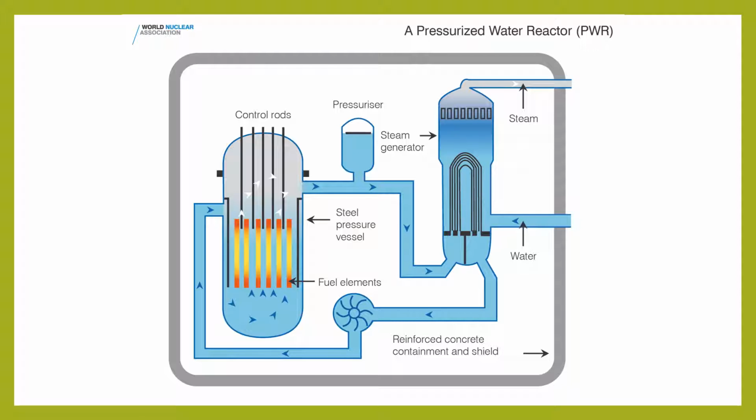The basic idea of this reactor is that water is heated to extremely high temperatures, but doesn't boil by being kept under high pressure. This water is then converted to steam by a steam generator in a second system, which in turn drives the turbines and powers the generators, creating electricity. In this type of reactor, water is used as both a moderator and a coolant. This type of reactor is especially interesting because the hotter the coolant becomes, the less energy is produced, making it very stable and essentially able to naturally control the reaction.